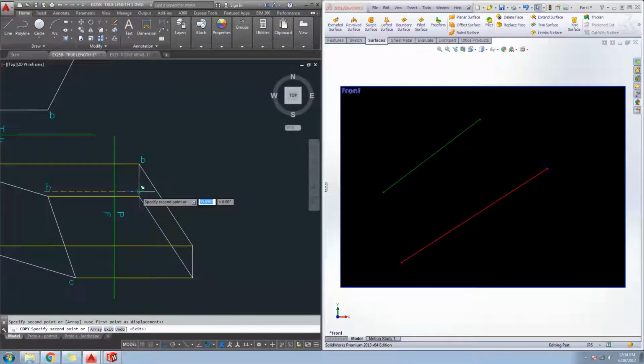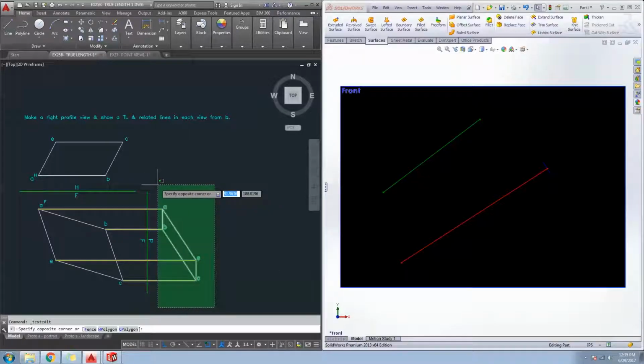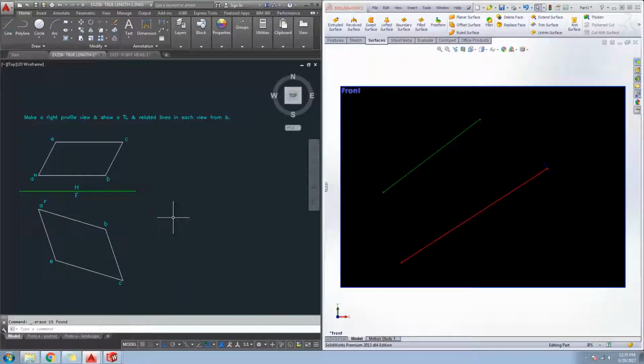And now we will identify each of these points. This one's going to be point C, that'll be point E, that'll be point B, and that'll be point A. And that A should have a superscript above it, identifying it as being on the profile plane. And then we would shorten these extension lines up. But that's the basic process for creating any view, really. So let's go ahead and delete all of that work we just did. That one too. Cool.